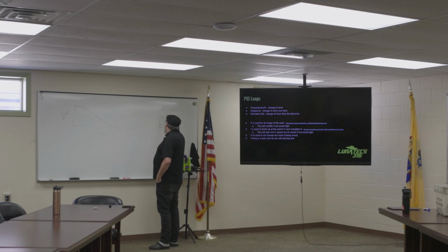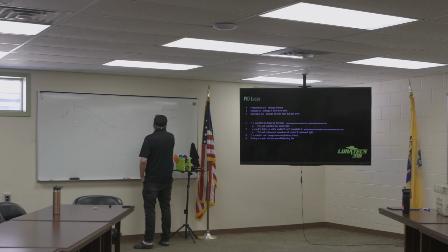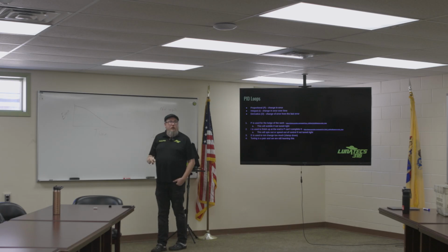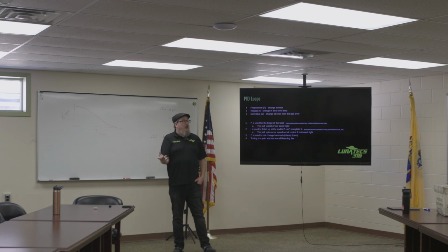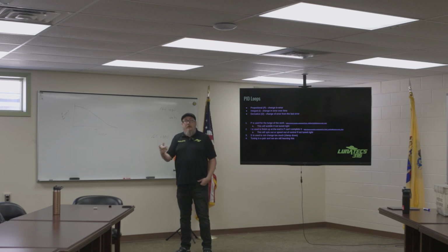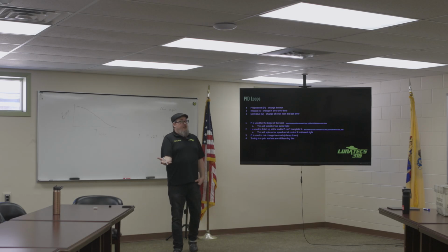So what I could do is multiply the number by, say, what? Let me think about this for a second. Let's say I want to go, I'm going to make it easier on myself because I'm lazy, 100 miles an hour. I can multiply it by 0.01. So if I'm at an error of 100, meaning what would be my speed if my error was 100? 0. So if I'm at error 100, I multiply that, and what would I get? 1. And we'll represent 1 as 100%.